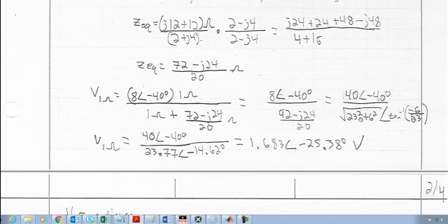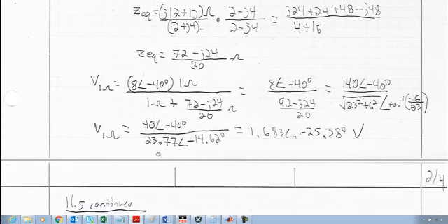And so this works out to be a phasor. I'm going to convert this complex number in the denominator back to a phasor. So my R is just going to be the square root of 23 squared plus 6 squared, and my angle phi is going to be the inverse tangent of negative 6 over 23. And so that, as a phasor in the denominator, works out to be 23.77 phasor negative 14.62 degrees. And just to divide these two phasors, remember I divide the two R values. That's what you see here.